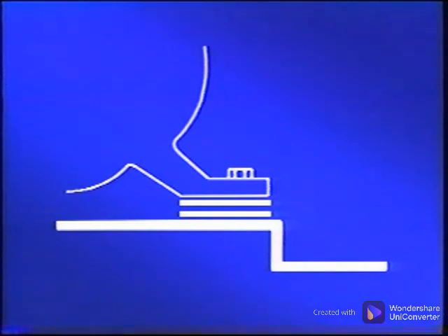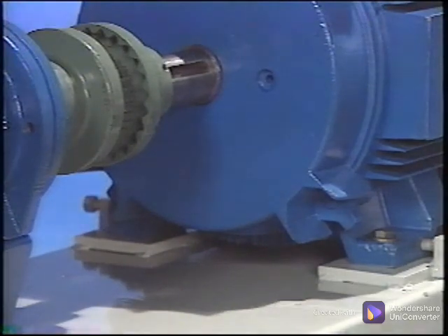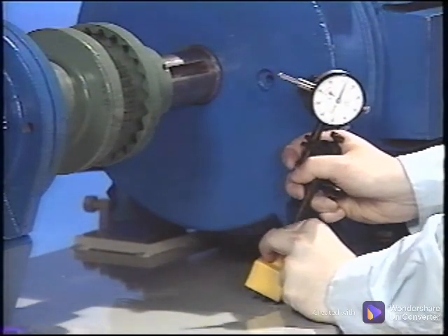There should be no more than 5 shims under any foot at the same time, because the stiffness of the foot decreases as the number of shims increases. If several shims are to be used on a foot, sandwich the thinner shims between the thicker ones. Measure shaft runout for a bent shaft condition and measure the runout on the coupling. To set up for measuring the shaft and coupling runout, mount